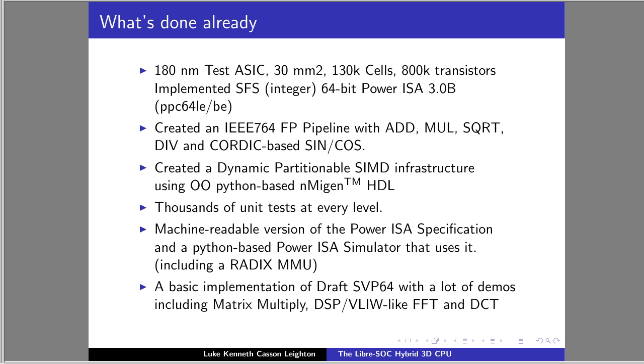It's specifically designed so that you can do the full inner loop of an FFT. But for SVP64, I decided that wasn't good enough and did the entire triple loop. So it will do an entire FFT of up to as big as you can fit into the register file.